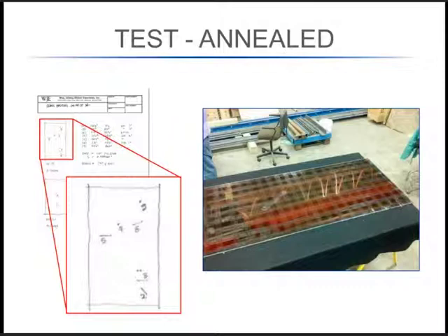And then on the right, you can see a piece of our glass. Because we're very interested on the annealed glass in finding out where the fracture origin is, we don't want the glass just completely breaking and falling apart. So we took some clear plastic tape and used it in the crisscross pattern you see there and put that on the compression side of the glass, so it wasn't providing any kind of additional strength. We placed that on there to try to retain the glass so that we can at least see the fracture origin.